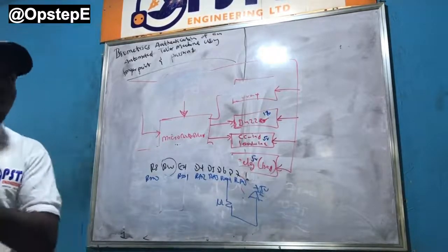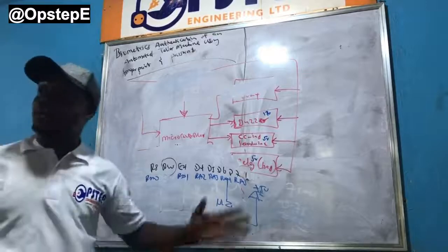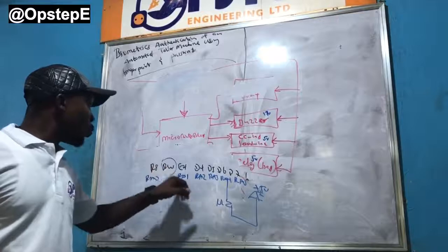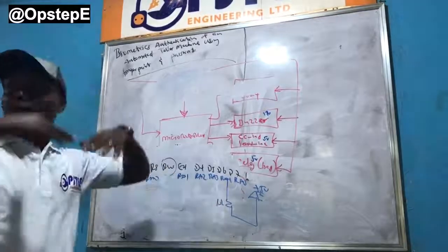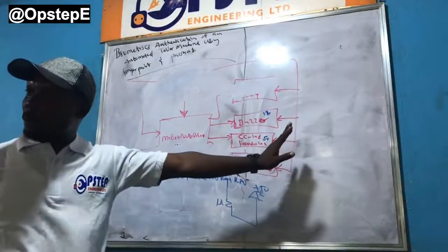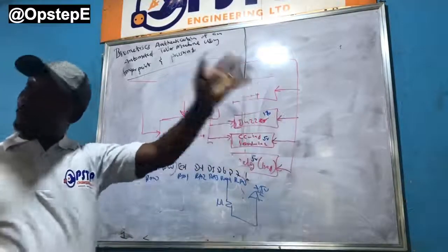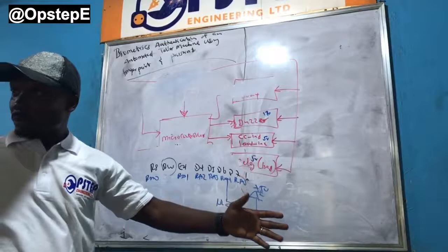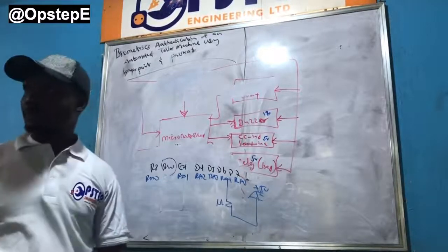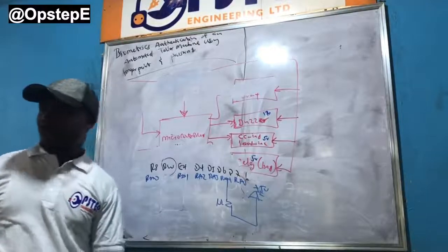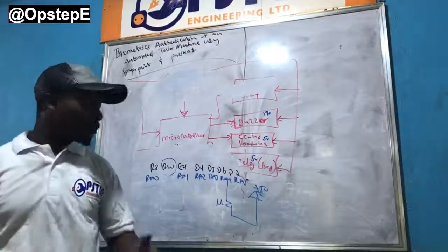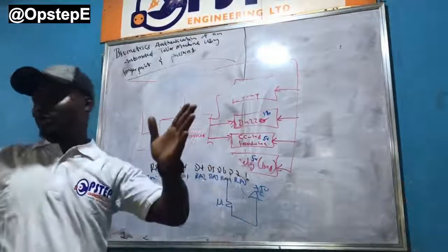So what I could do is maybe split the LCD. Let RA0, 1, 2, and 3 be for data. Then I can go back to my port C and take 4 from there too, for the other side. Are you following? But it's not going to help my PCB layout, because the port A pins are not in the same position as the port C pins.